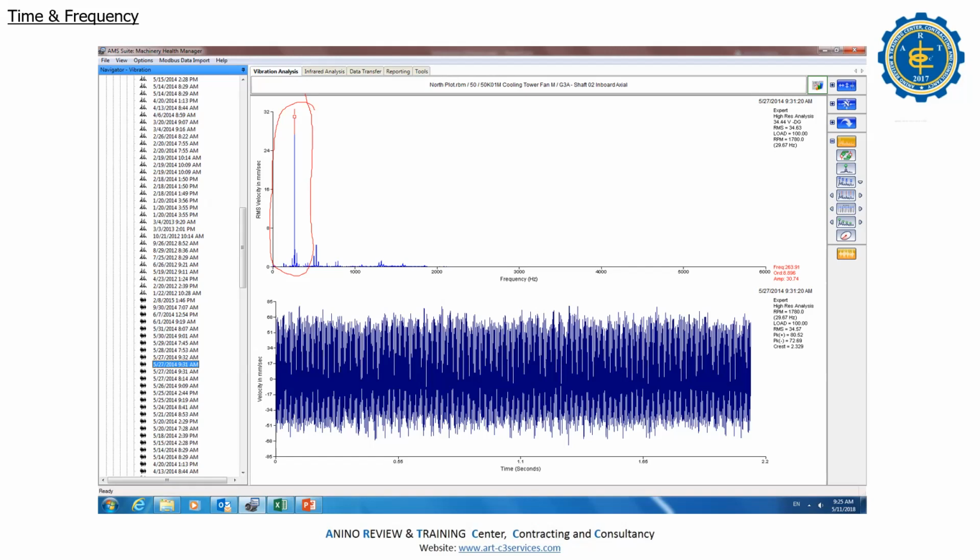So I tell my superior, okay, high vibration dominant in 1x, and 2x is low. And then the superintendent told me, okay, just monitor, because only 1x, maybe the structure, the bearing frequency is not so bad. So okay, just monitor, then in time it will go down.